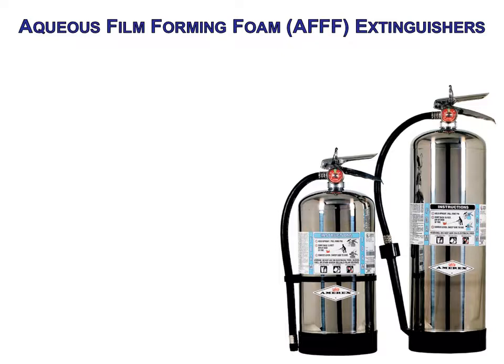AFFF extinguishers are foam extinguishers. These are suitable for Class A and Class B fires. They contain an AFFF concentrated mixture with water, have an air aspirating nozzle to aerate the foam solution, and are expelled by compressed air or nitrogen stored in the tank.